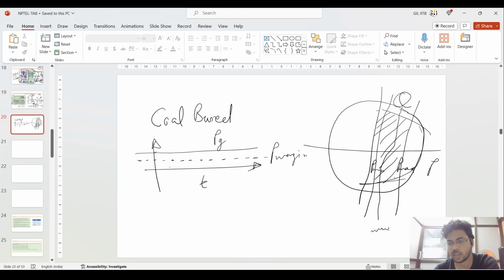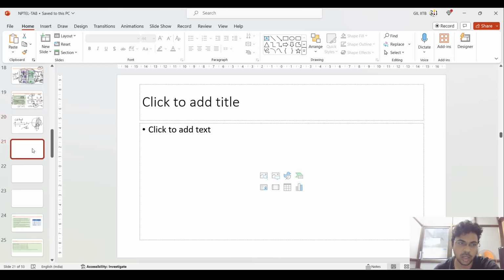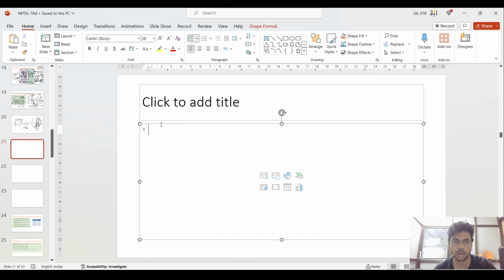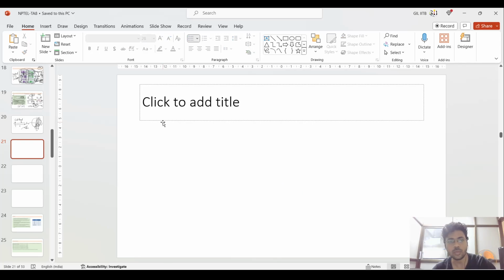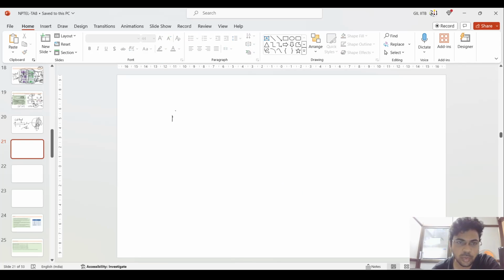Without going to the P max, you provide a certain margin. The margin is such that when a delta f change happens and a sudden large amount of power is demanded, you can utilize this above marginal power, that is the P max minus P marginal power. And the same concept is utilized in the RE situation. If you see the RE situation in the PV based power plant, what is happening there?